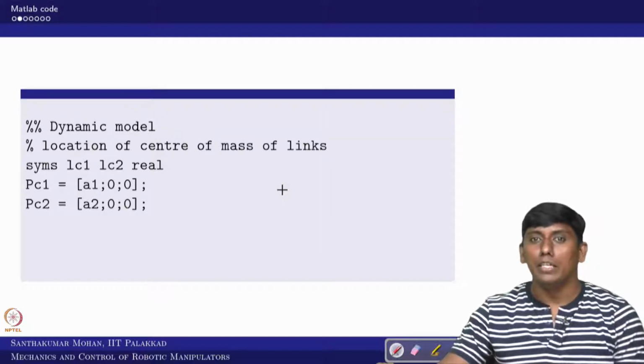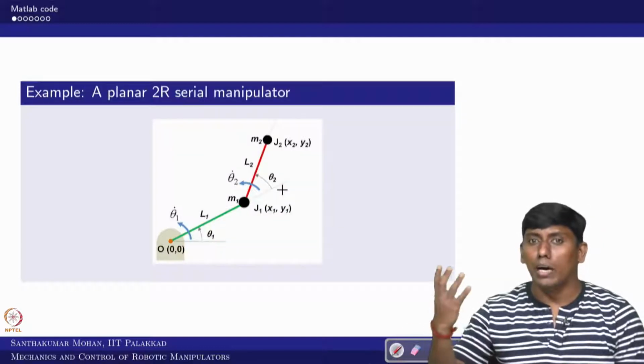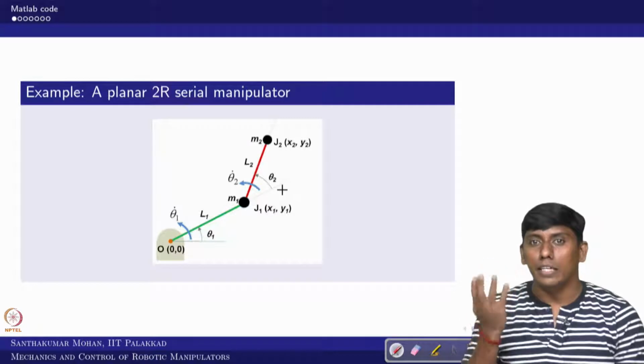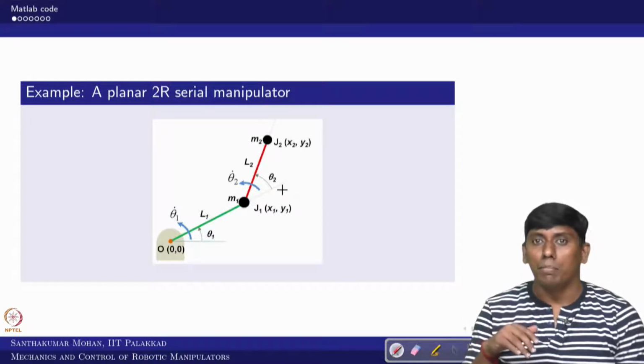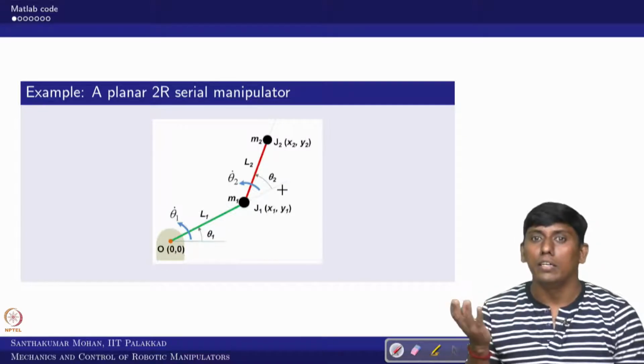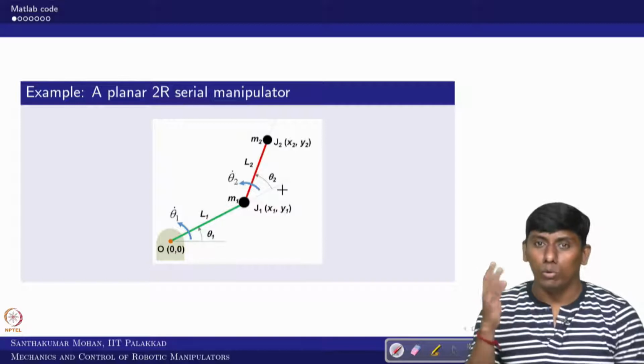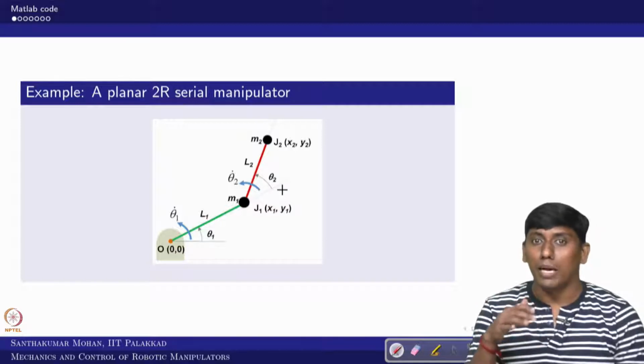First, what we need to know: till now in velocity kinematics, we have already shown how to derive the DH parameter with the help of frames. Once you obtain the DH parameter, you can substitute it in the MATLAB code. You can find the rotation matrices and position vectors of the individual joints. These all we have seen.